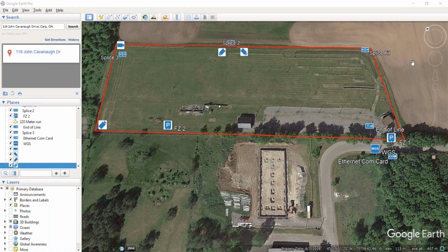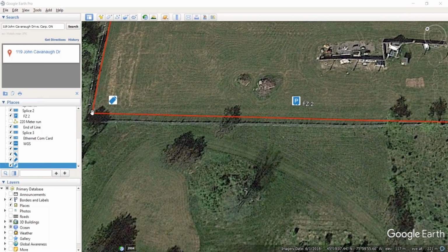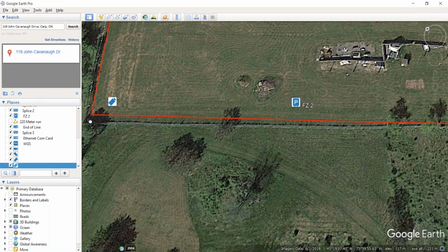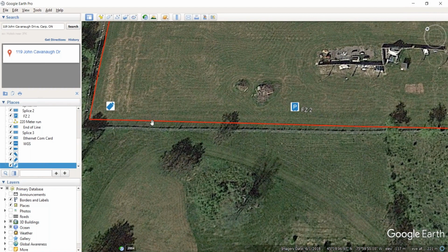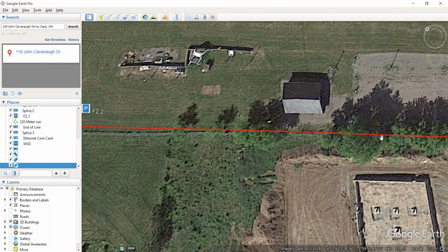Been that Google Earth is accurate within about, believe it or not, 1%. It is that accurate. Where we see discrepancies is human error. So I'm going to zoom in for just a moment here, just so I can show you something as an example. When I drew the polygon, I actually have my line slightly inside my perimeter line. That's where sometimes we have a discrepancy, so we may be off a bit. However, as you go down, you also see that I'm outside the perimeter line here. So we're very, very close, we're accurate.